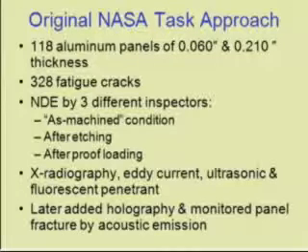They were inspected by X-radiography, eddy current, ultrasonic, and fluorescent penetrant, and this was the early 70s, so some of those techniques have improved. Later we added holographic inspection, and we also did acoustic emission because all of these parts were pulled to failure and the physical crack size measured. So we not only knew that the crack was there, we knew what its physical dimensions were, and that was the program. And for those of you who are near, one of my tie jacks is one of those original cracks from that program.